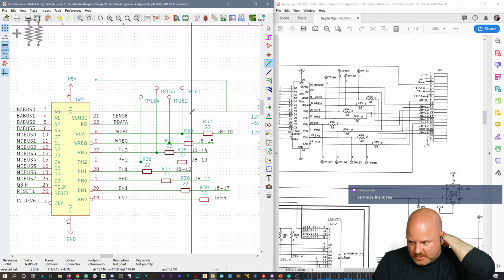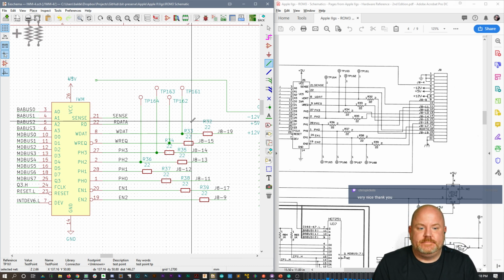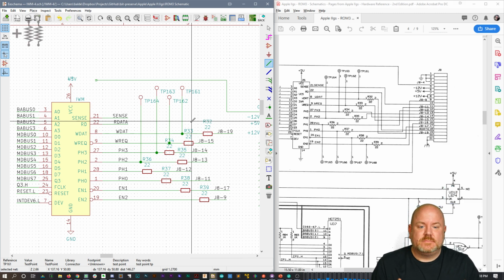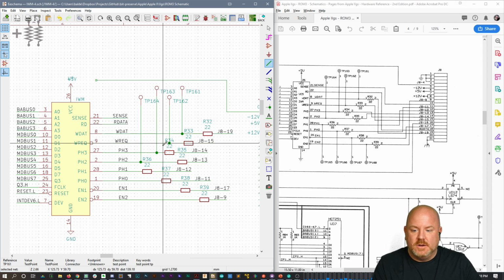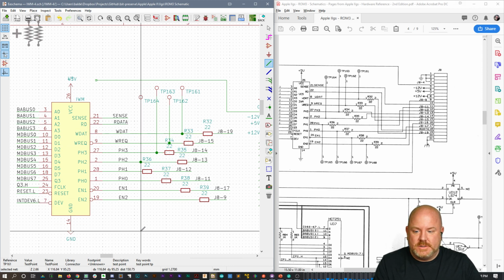Do onboard resistors generate more heat, causing another concern for spacing? I wouldn't say they generate more heat, they just generate heat. Especially if it's a pull-up or something, it's not going to be a lot of current. But when an IC is designed or manufactured, the goal is to keep it as cool as possible. And so any additional heat sources are not usually preferred.